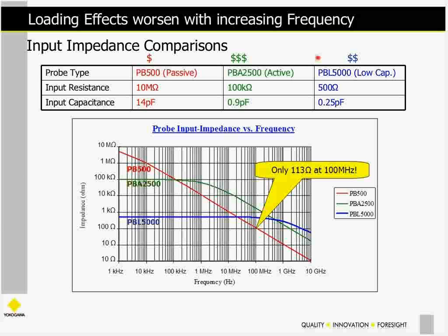Okay, and then here's the Z0, the low capacitance probe that I told you about. This is the transmission line probe, and we have this one set up for 500 ohms. These can also be set up for 900 ohms. So this one starts out at 500 ohms, pretty much stays there all the way up to several gigahertz. So obviously your circuit has to tolerate 500 ohms. But what it does best is its ultra low capacitance, and that's what extends the frequency range on it.